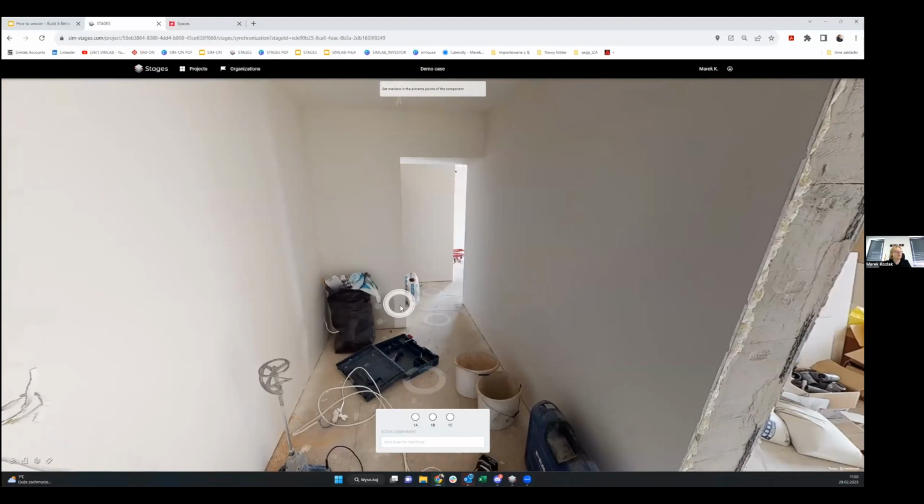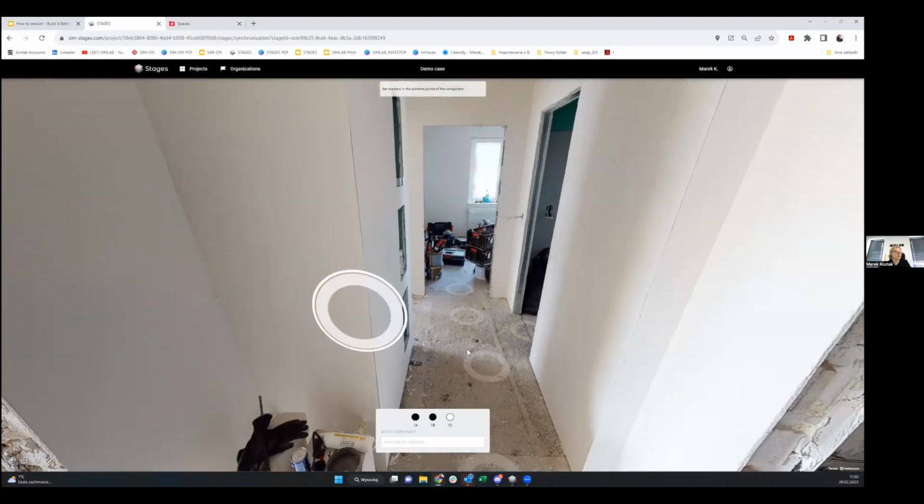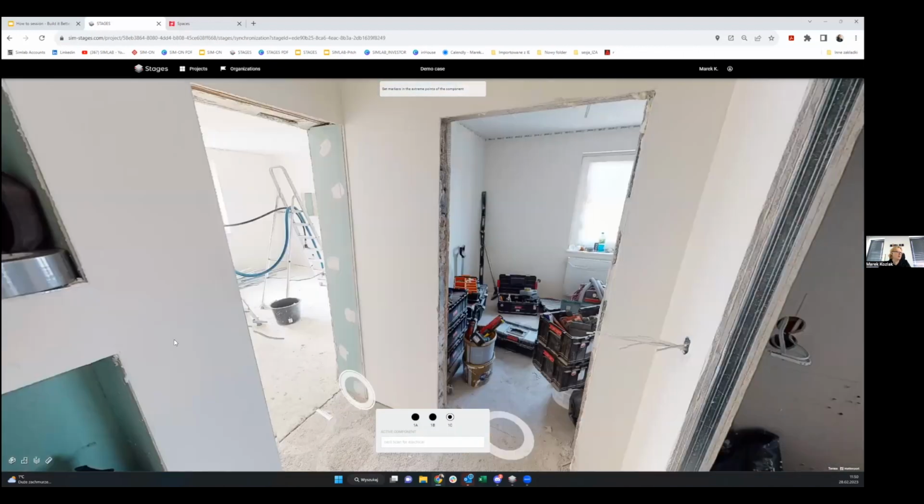But what the wizard is saying here, I have a big resolution, so it's small letters. It's saying that please point 1A, 1B, 1C as the characteristic points in your Matterport model. So I'm selecting here point 1A. I select the next point 1B, for example, here, and then maybe let's say something for the calibration, something in another corner of the facility. Let's put 1C in that moment.